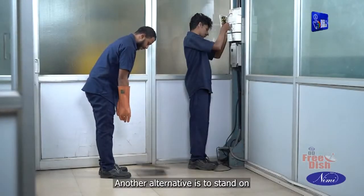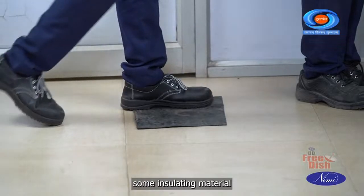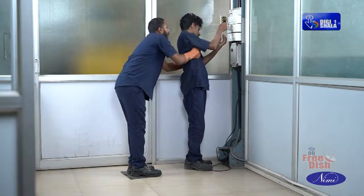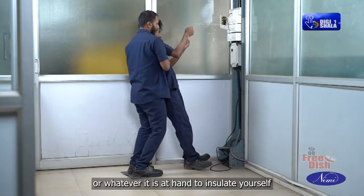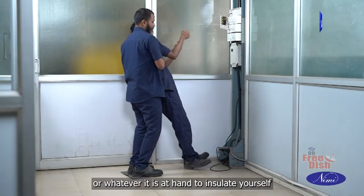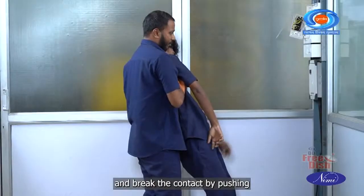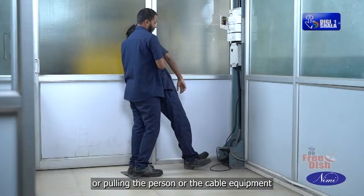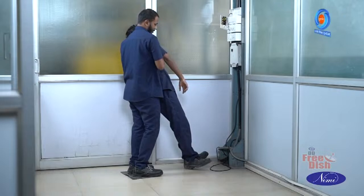Another alternative is to stand on some insulating material such as dry wood, rubber, plastic or whatever is at hand to insulate yourself and break the contact by pushing or pulling the person or the cable, equipment or point free.